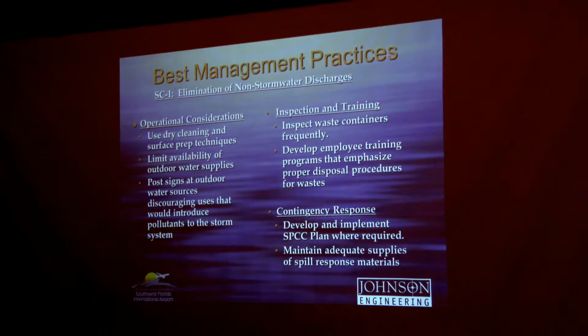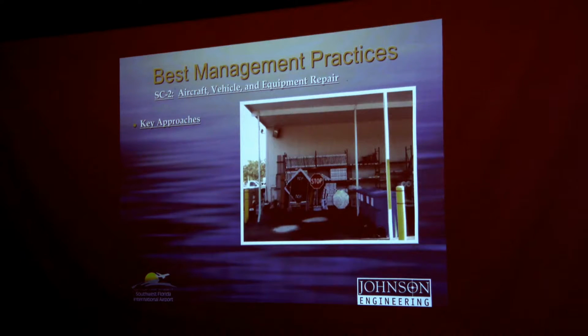Operational considerations for the elimination of non-stormwater discharges include use dry cleaning and surface prep techniques where you can, limiting the availability of outdoor water supplies, posting signs at outdoor water sources, discouraging uses that could introduce pollutants, inspecting waste containers frequently, developing employee training programs that emphasize proper disposal procedures, developing and implementing SPCC plan where required, which we're going to talk about a little bit later today, and maintaining adequate supplies of spill response materials.